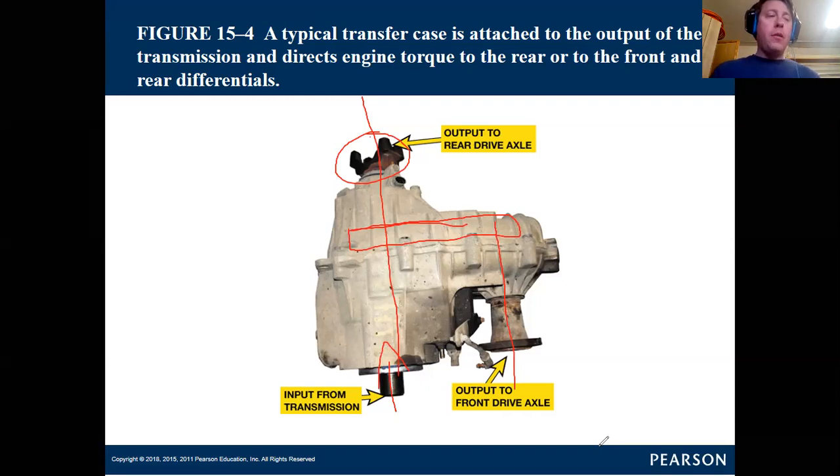We'll talk about the failure of these components in the next chapter. But just to give you a little bit of an idea, a common problem in these transfer cases is that the chains themselves will start to stretch over time. That can be an issue, and we'll discuss some of those drivability diagnostic procedures and failure analysis in the next chapter.